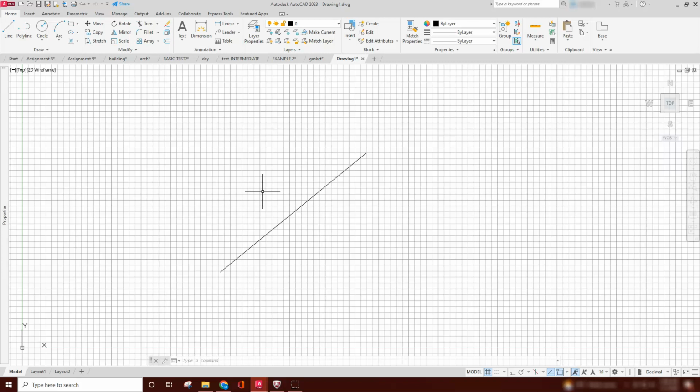I'm doing this mainly because when you're going to print something, you don't know the exact size of it. Now, I'll caution you that if you have multiple drawings inside of your model tab, basically a drawing here and another drawing here and another drawing here, publish is not going to work for you. In that case, I would recommend you set up different layout tabs for each of the sheets.